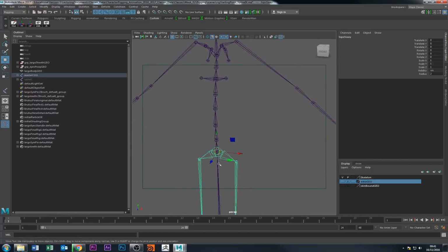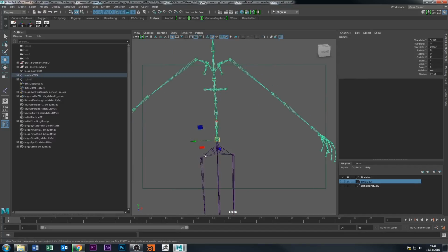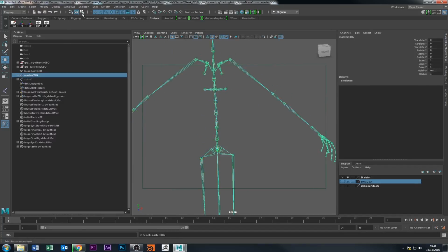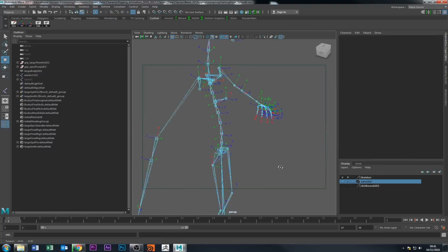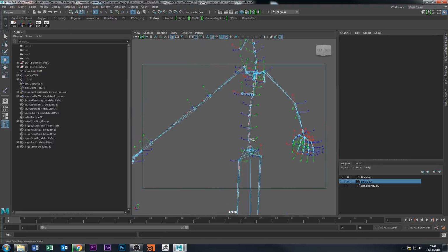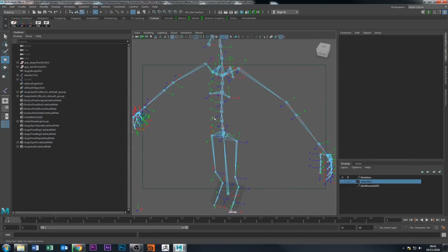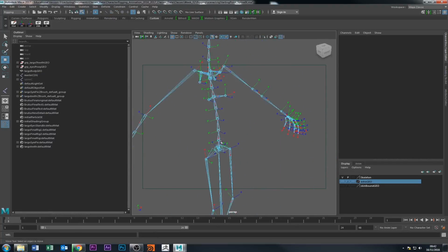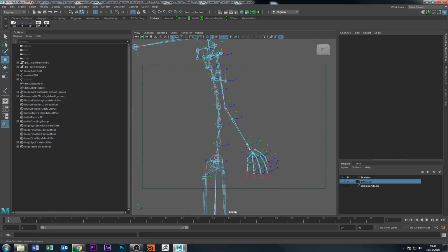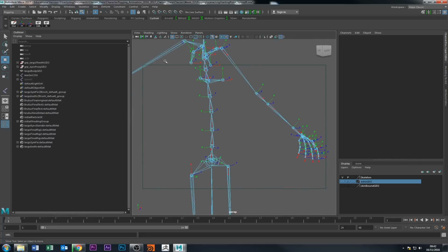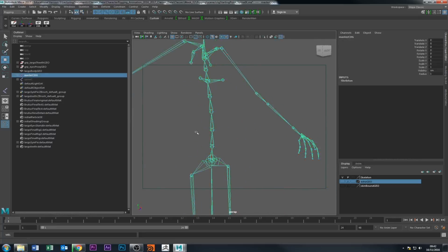First of all, I just want to check the orientations of the joints. So I'm just going to select the whole rig and see that everything is working. You can see the spline, the IK is all there. They all have harmony. They're all pointing the Y in this direction, and the twisting angle is the X. So that's fine. So let's start working on the IK spline.